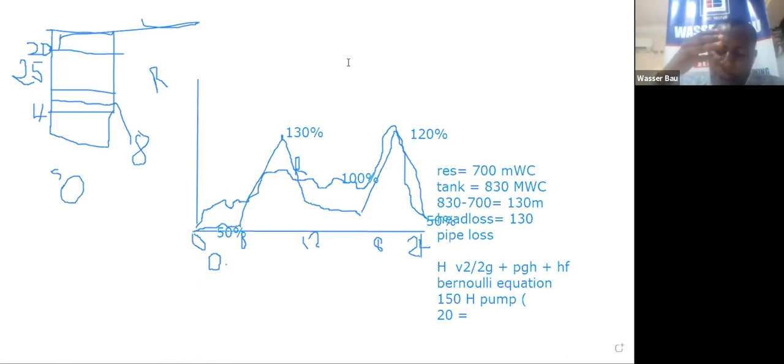You need to extract water at a defined rate for a 24 hours period, and you monitor the drawdown of the well. After plotting the drawdown with the extraction rate, you can design the limit to set the pump. Then you can also define the properties of the aquifer, to say, okay, this aquifer has a good recharge rate. This aquifer is sustainable.